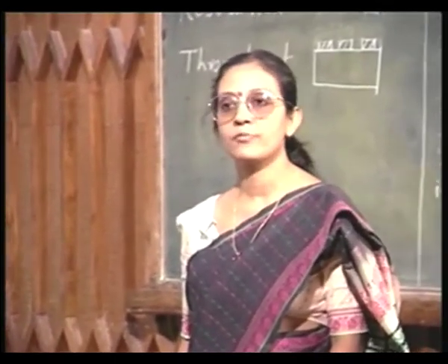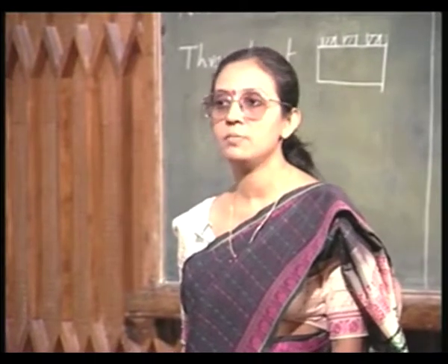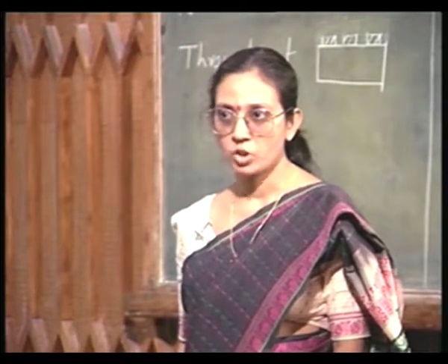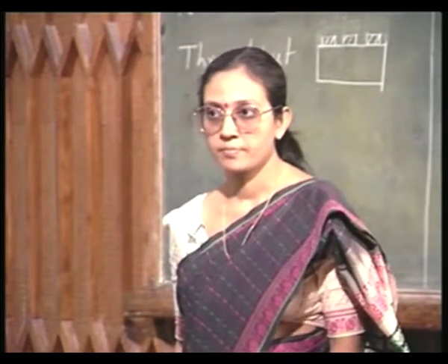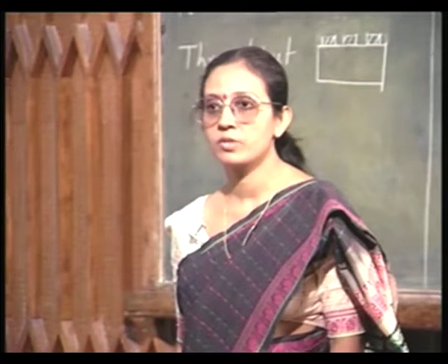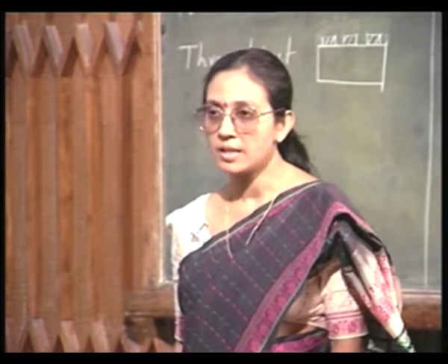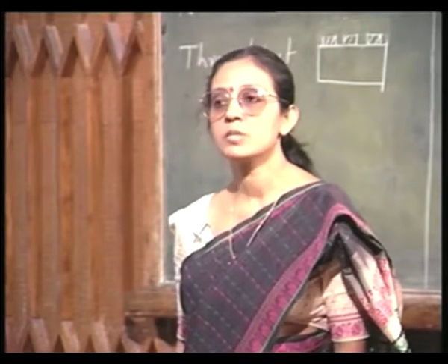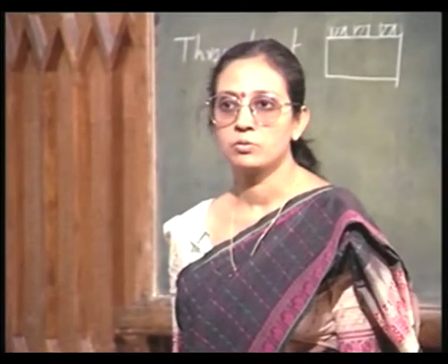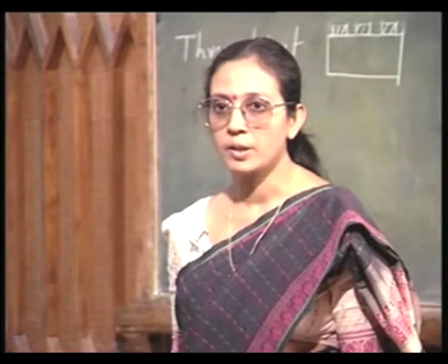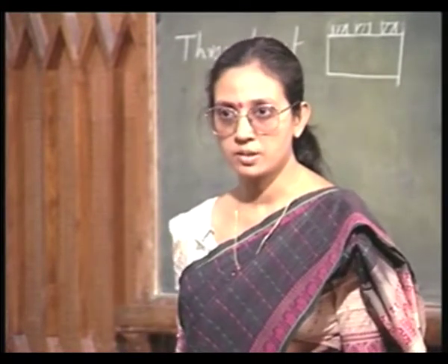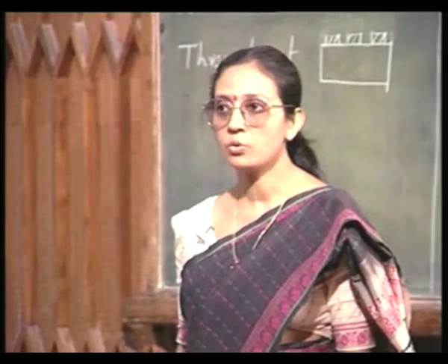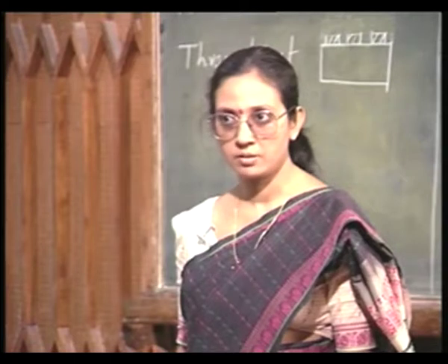I will go one step further and say resolution actually means that if I have, say, a 1 micron feature size in the mask, does it stay 1 micron in the silicon wafer, or does it become say 1.2 micron or 0.8 micron, that is whether it increases or it decreases. How good is the resolution, that is how close to the mask it is.